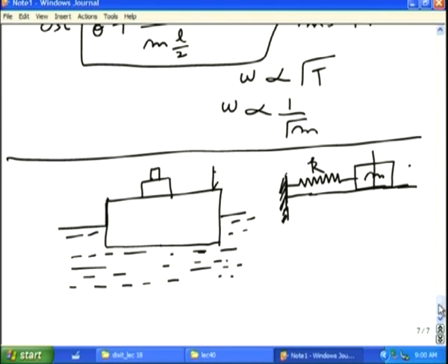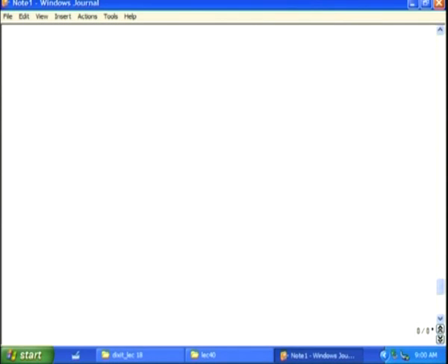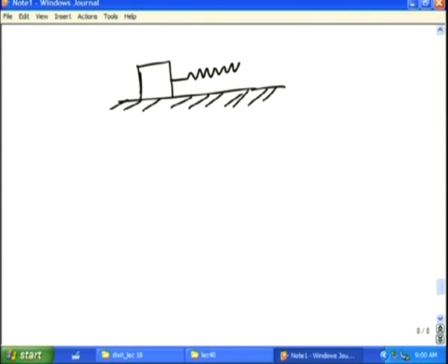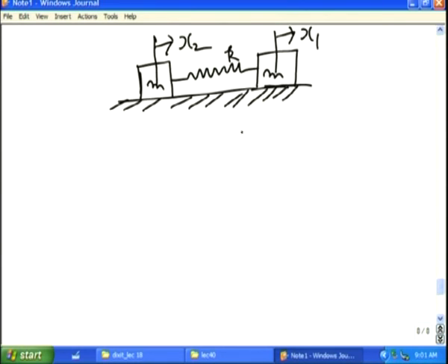Now, lastly, we have discussed only single degree of freedom system, but let me just do the simple example of a 2 degree freedom system, so that you can understand that this can be easily extended to multi-degree freedom system. Consider the motion of this x1, this is x2. There are two masses m, both are of equal mass, we are just assuming it, and then this is the spring stiffness k. Let us make the free body diagram of this mass. So, this is mass and then there is a spring force that is k x1 minus x2.